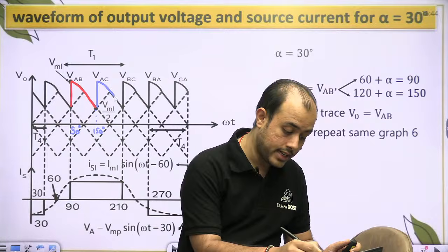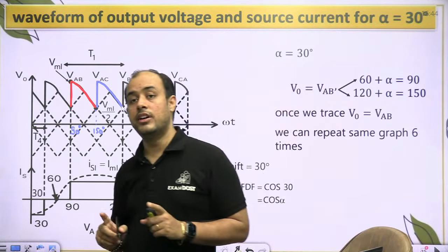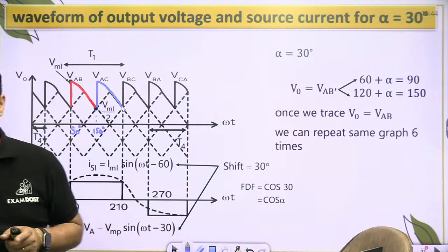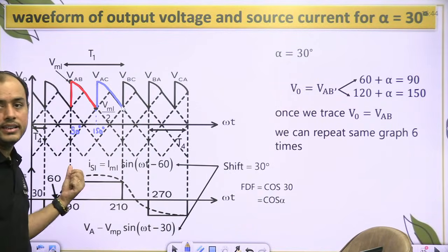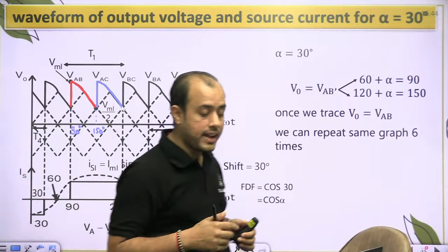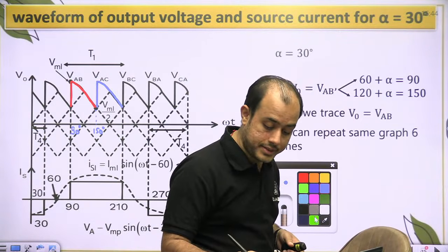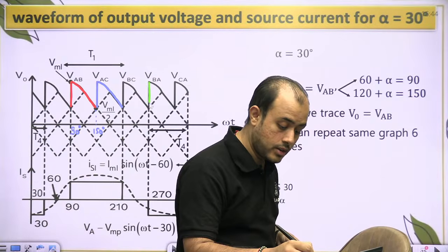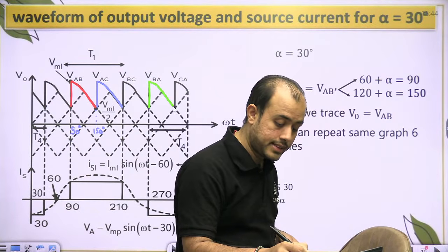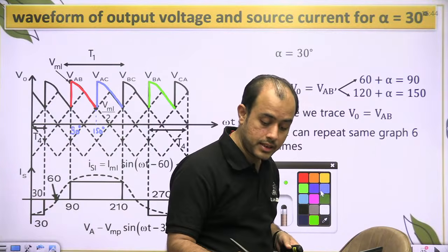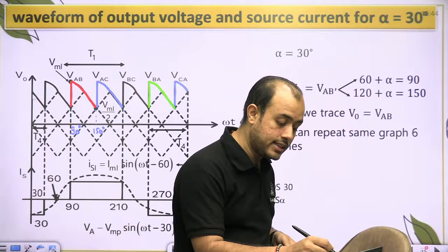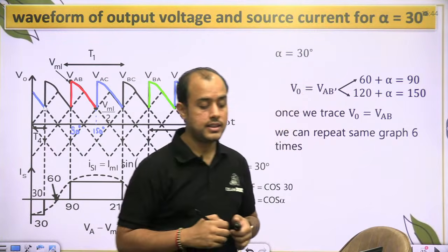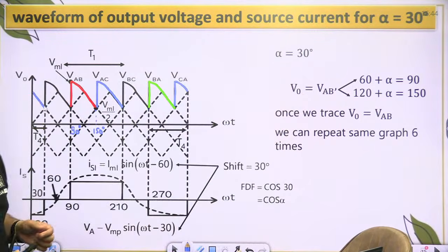Now beta, whenever AB and AC are conducting, it means one thing, that phase A is supplying current to the load. So current of A is I naught. But when the voltage is BA or CA, means A is the second subscript. It means beta A phase is carrying the current back to the source. So their current is minus I naught. Minus I naught आता है.